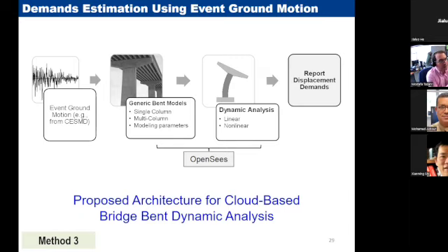So as, let's say, an inspector, the failure means you see multiple bar buckling, multiple bar rupture, or your bridge column is kind of deformed, as you can see on the screen under the dynamic tab. So if you see large residual displacement that cannot be recovered after earthquake, your bridge deck is kind of tilted significantly, no one can pass along, or you see multiple column or bar rupture or buckling, then that's your field failure.